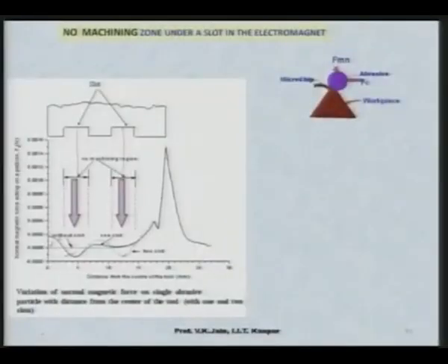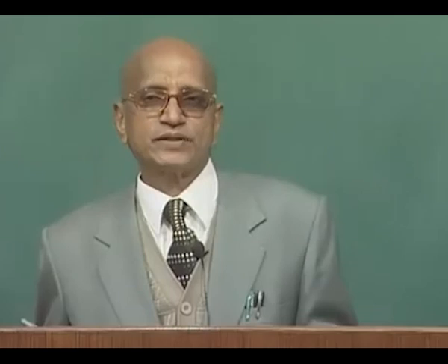So, really speaking, this will not affect the negative force too much, because at that particular time no machining will take place. But in the rest of the places the forces are higher than in the case of no slot condition, and these forces are responsible for increasing the finishing rate. That is why we found that with a slot in the magnet, the finishing rate is higher compared to the case when there is no slot.